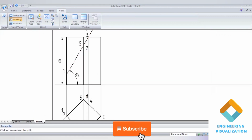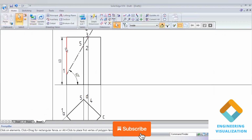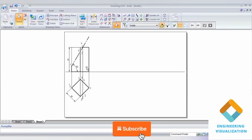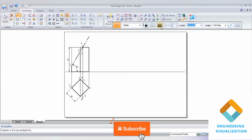We have to darken only the portions which have been cut by the section plane, the retained cut portions. The other lines I'm going to make thin lines. By selecting these lines, I'll make them thin lines. Now we got the cut portion.